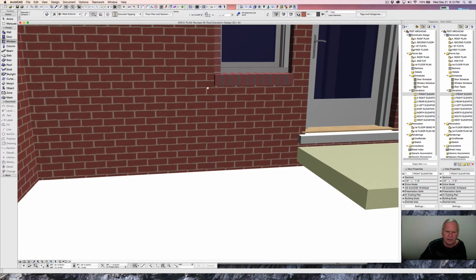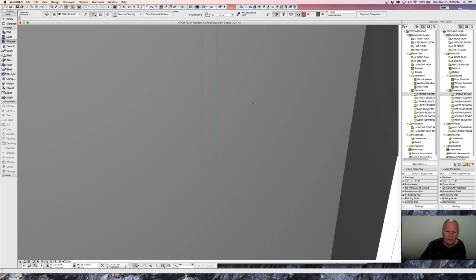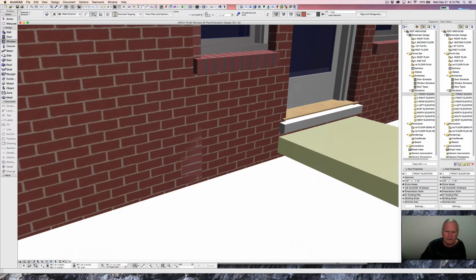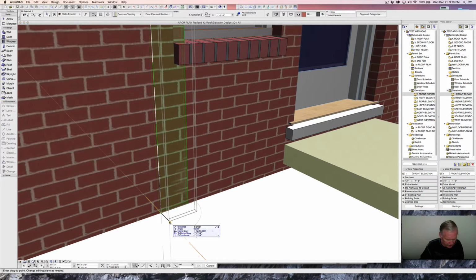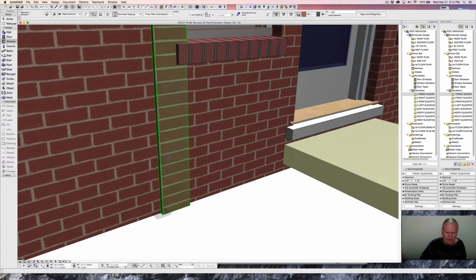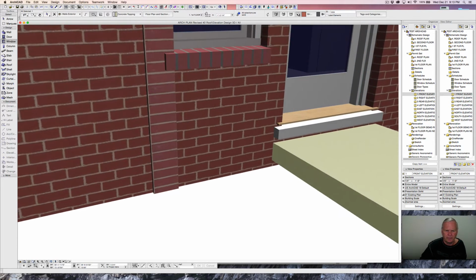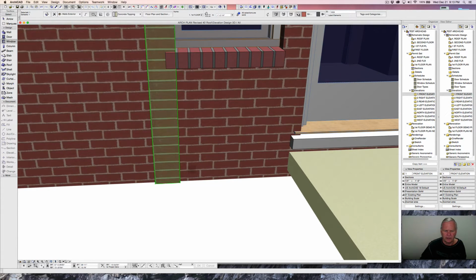And you'll see that that sets up. Well, I zoomed out a little too quickly, but actually it didn't. It set it back into the wall, so we want to come out. We know 1 inch, so we'll just pull it out and go D, 1 inch. Just set the other face to it. Okay, so we've got that one. Looks like we have a little sill conflict.